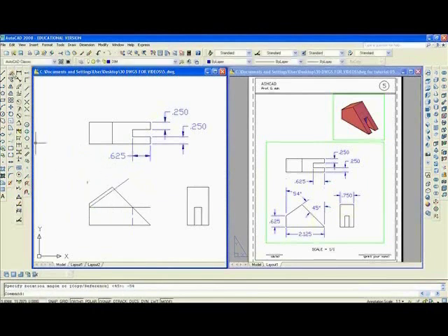That means I have to erase this and trim, TR, enter, from any line, that, and I can erase this line, fillet this area here, match property, because I want everything to be on the right layer. So I want that line to be on layer 1.